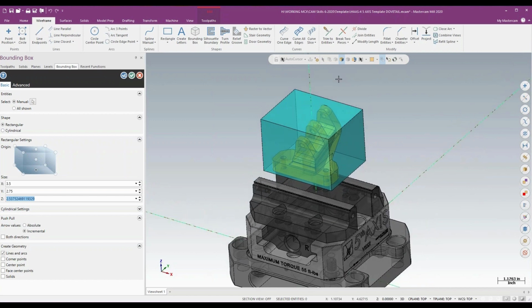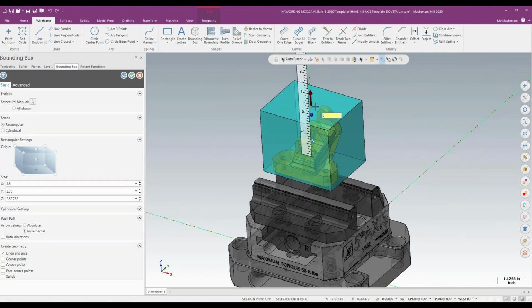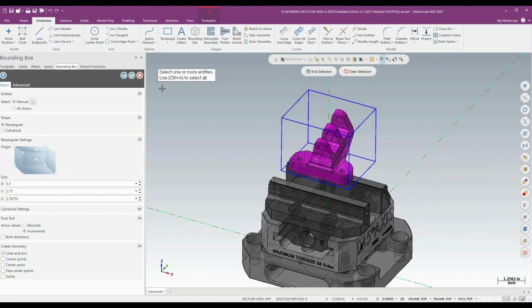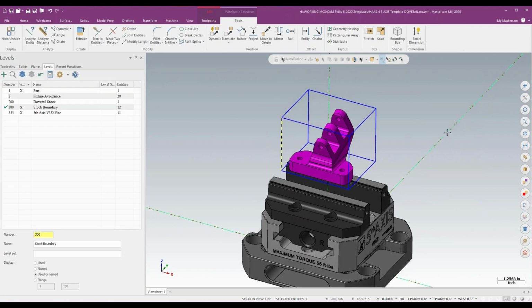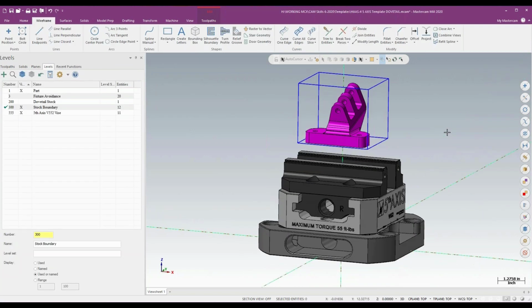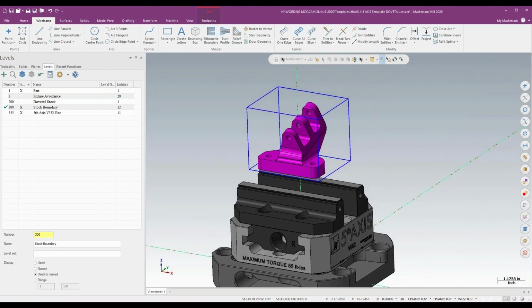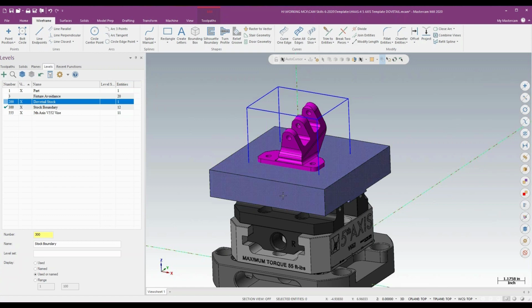And I'll go ahead and grab the top of that surface there, and I'll just increase Z up by, say, 1/4 inch. Okay. I'll go ahead and green check, and there is my basic boundary of material. Now, I didn't extend it on the bottom because I don't need to, okay? Because what I'm going to do is turn that solid piece of stock back on, and I'm going to resize it based off that bounding box. And I can do that really easily.